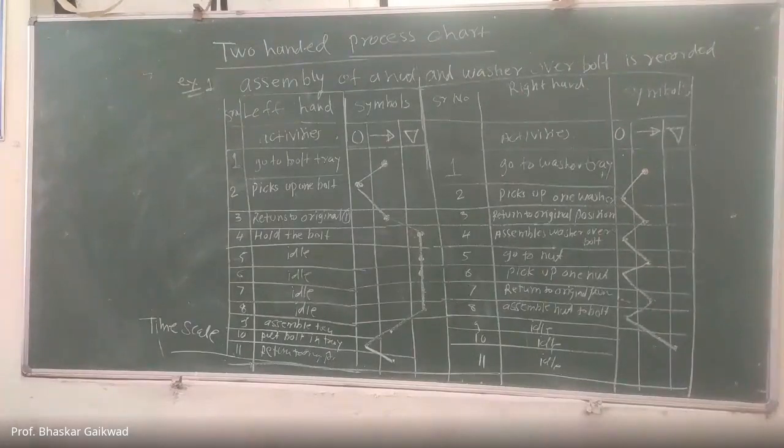So next is our flow process chart. When can we use the flow process chart? Whenever there is a movement of jobs along with the operations, along with the delay. So once the materials we demand from the market come to our workshop premises or industrial premises, after that hacksaw or band saw cutting operation will be there. After that, the material goes to the machining section. Transportation is there. There the operation will take place. After that, inspections will be there.